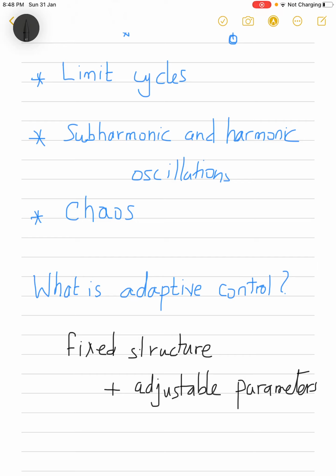And adaptive controllers are suggested to deal with the uncertainties that could exist in a given system, and as I mentioned before, these uncertainties could be classified as parametric uncertainties, like for example a motor that we don't know its friction coefficient for sure, or the inductance or the inertia or whatever, we don't know the parameters for sure.